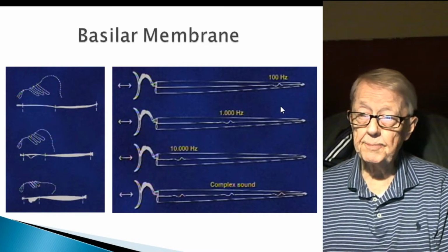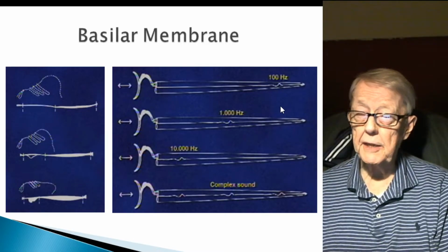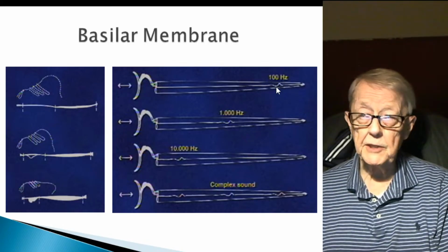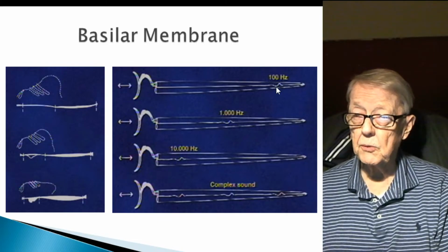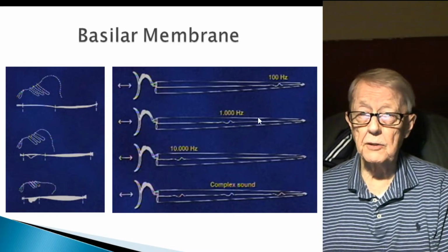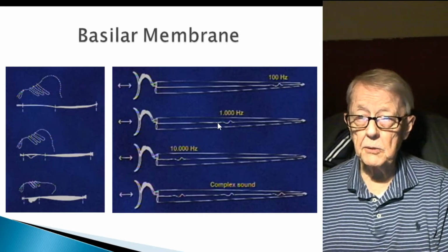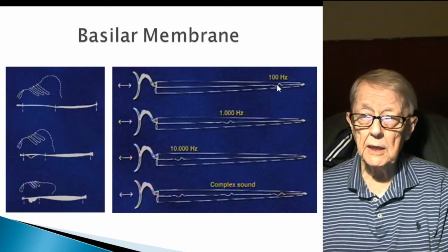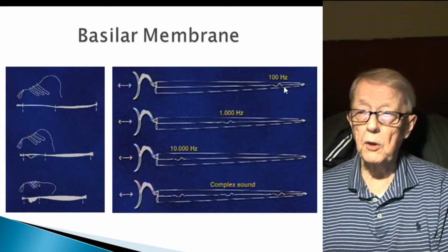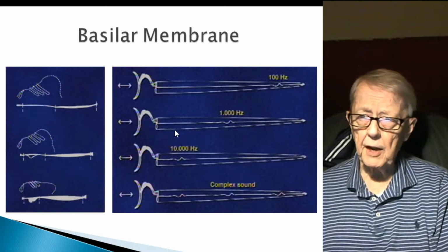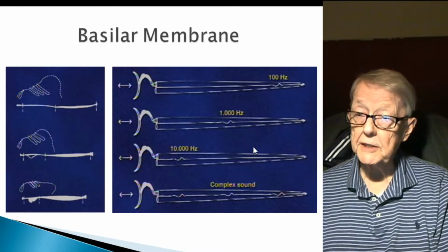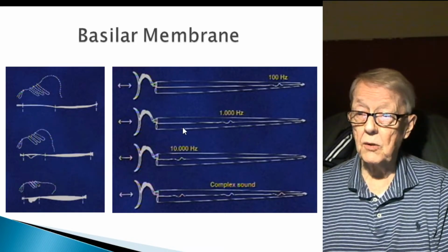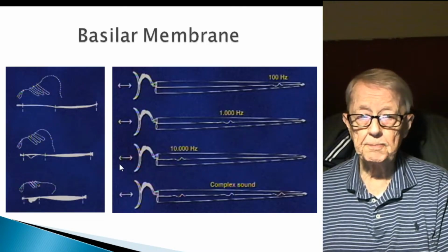Being a circuit designer for telecommunications, especially switching, I'm fully aware that the frequency the telephone switch was originally designed for was only 4,000 hertz. So the frequency was here, and we gave more attention to the low frequency to make it more accurate than the high frequency. That's because voice only goes no more than 4,000 hertz, whereas sound, music, can go up to 20,000.